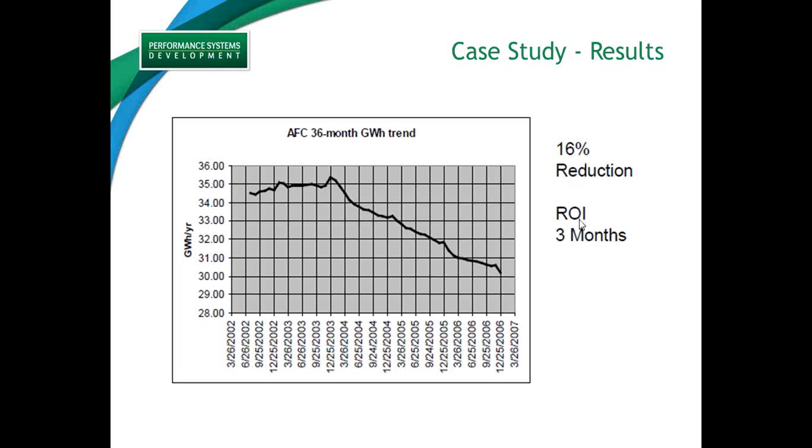Just going to show, this is an example of what the ECAM tool can show you. The ECAM tool can look at meter data, like your electricity data, all interval data or monthly, but typically for these buildings we're looking at interval data. And it can also be used to do the actual measurement and verification of savings after you establish a baseline and measure before and after performance.